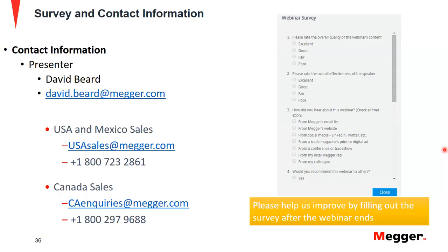Beautiful, thank you. So Mohit, I have a question for you. Can overcurrent elements misoperate for faults not on the protected line? Yeah, absolutely, especially on radial feeders. I'm assuming the question was asked related to non-directional overcurrent elements.